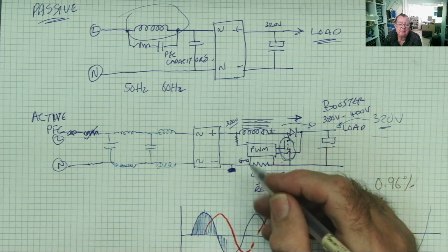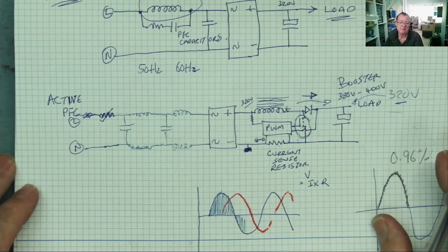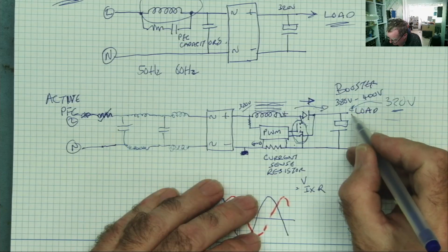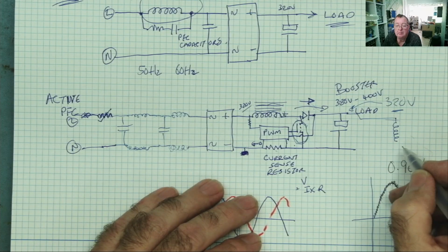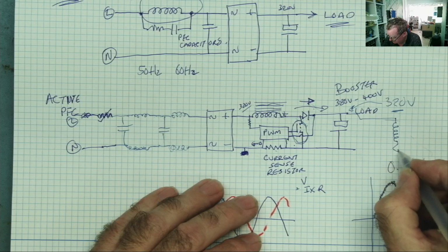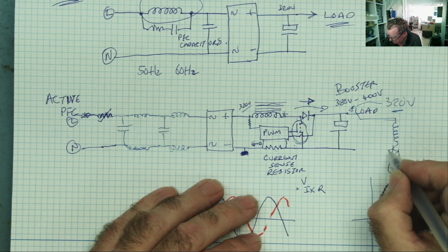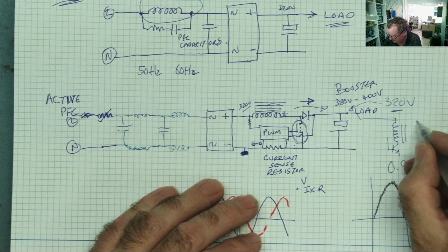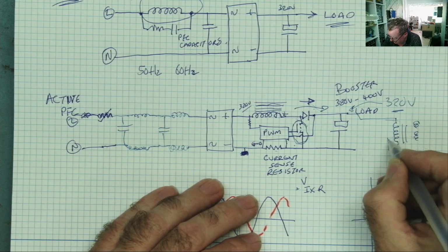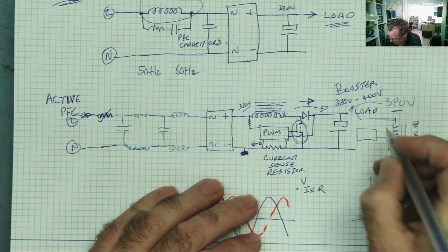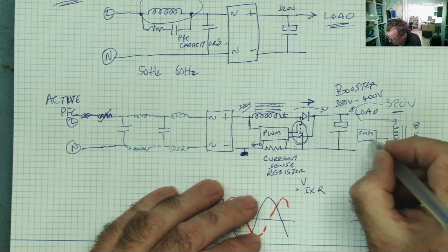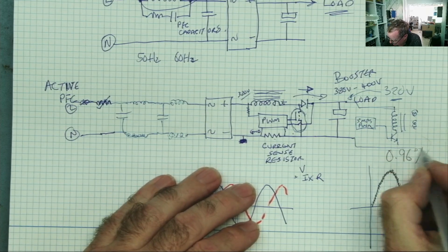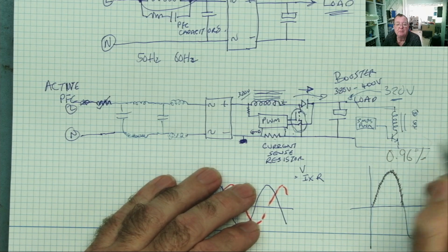You also find in some power supplies, if we just complete this diagram, you'll basically see what I mean. So this is going into your, I'll draw it like this, it doesn't really matter, this is not most power supplies, but this is going into your switching circuit like this, okay? MOSFET or transistor, this is your primary, these are your secondaries, and this is controlled by the switch mode power supply pulse width modulator. So this again is switching very rapidly. This is your switch mode power supply, okay?